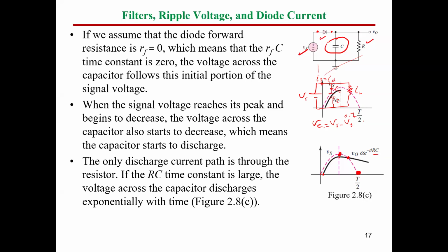RC is the time constant of the circuit, which represents the capacitor and load resistance. This is a first order differential equation, so it can be solved in order to know exactly the value of alpha. So this is the expected waveform we will have for the capacitor volt. And you know the capacitor volt is connected to our output, so this is going to be the output volt.